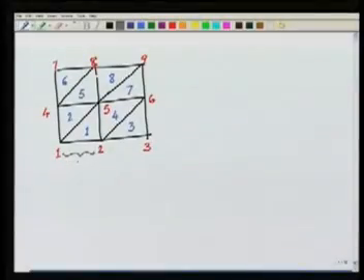Let's take further that the straight edges of the elements are of size h. So both the straight edges of a given element are of size h. That is, my domain is of size 2h by 2h. For this domain, I would like to do the element stiffness matrix calculations using the linear approximation over the domain. So let's go through the steps that we have done earlier.